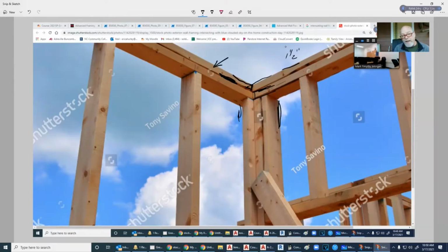So we just put this spacer in. And again, if our rafters do not hit directly on here, we have to use a double to transfer that load down on the stud. That has to be there. But if we were to line everything up perfectly, then the only reason we put this on there is to keep this height the same all the way around the house.